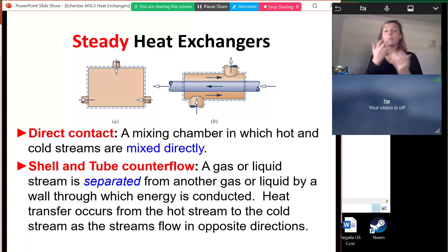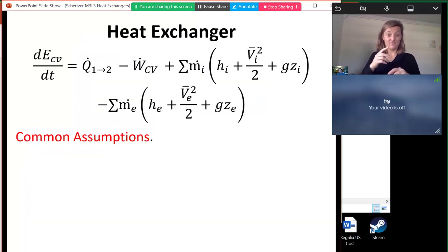If you think about maybe the radiator in the front of a car, you have your radiator fluid moving through one side of the heat exchanger, and then as your car is moving, the air flows over the fin apparatus that you see in a radiator, and then there's a cross-flow heat exchange between these things. So we're more interested in something that looks maybe like a shell and tube heat exchanger, or we'll talk about different geometries as well, but where our flows don't physically mix, but they still transfer heat between the different flows.